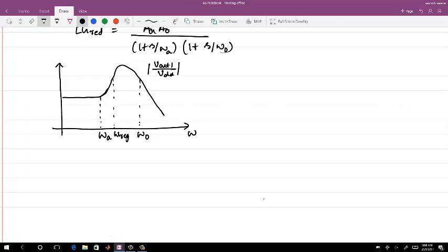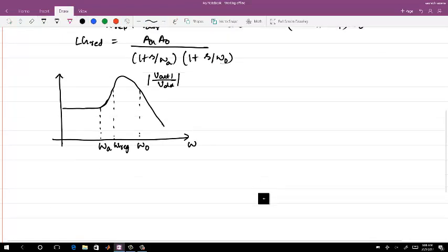Now the thing is that if we want to improve PSRR, we can make omega O dominant, but making omega O dominant actually comes with a larger capacitor which you need to use for having a stable loop. Okay, so in the replica, we still maintain V out 1 by VDD. Another thing which comes, if you look at the translation to V out, if we have some other transfer function, maybe a low pass filter, right, which can be V out. If V out 1 by V out 2 is something like this, you do not need to compromise on the larger capacitor, on the size of the capacitor in the replica, in an actual regulator. Okay, and this is actually what is happening when you use a replica based regulator. So look at the transfer function, which is V out 2 by V out 1.